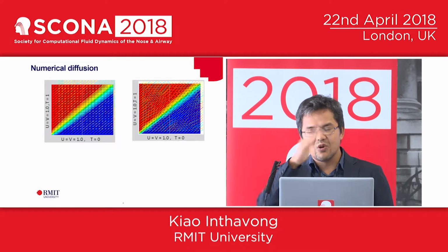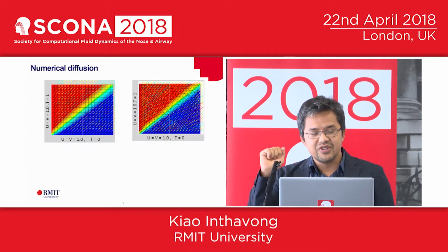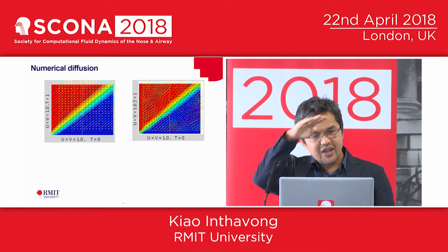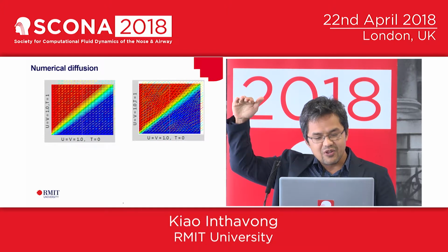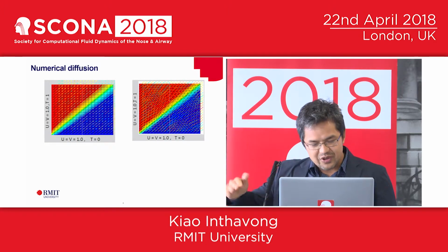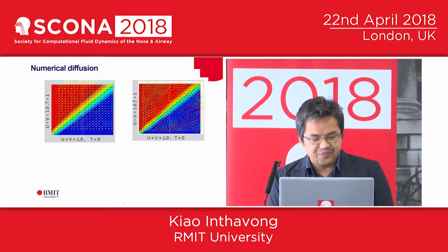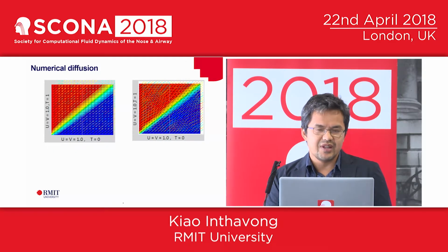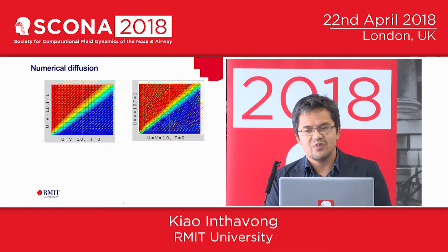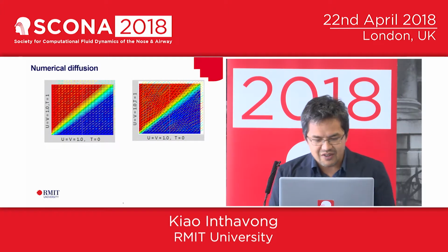So if you draw a vertical or horizontal line across that geometry, you should get a step function where it'll start at 1 as you go along the red line and then immediately drop and go to 0. But you see that in a lot of the finite volume models, they will interpolate, and so sometimes you don't get that perfect step function that you're after.